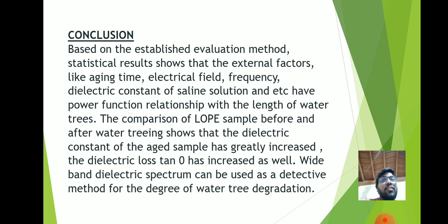before and after water treeing shows that the dielectric constant of the aged sample has greatly increased. The dielectric loss has increased as well. So, wideband dielectric spectrum can be used as a detection method for the degree of water tree degradation. This is about my topic.